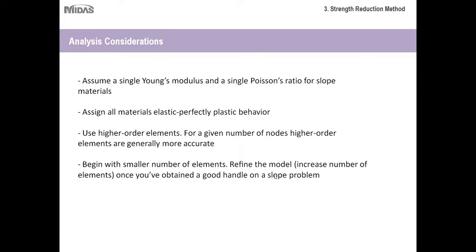So once again, for those of you who are still new to finite element modeling, when you first create your initial model, what you want to do is create a model with larger element pieces. Another important thing to remember is that when you increase the number of elements, or when you make your elements smaller, the analysis takes longer to run, but the results are more accurate.